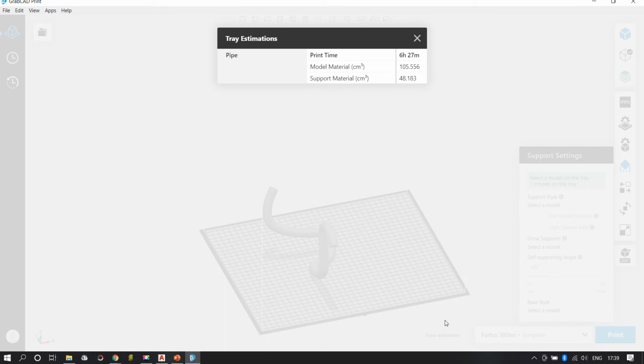Just like a monkey, you cannot orient it in all the possible directions to see how the support material is getting changed. You have to use your own common sense. Before orienting, you have to use your visualization capacity and determine. In this particular figure, of course it is difficult, but for some definite shapes when you are going to print, it is not that difficult to determine how to reduce the support material.